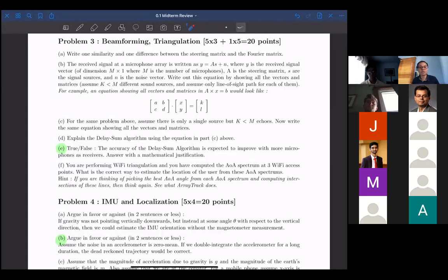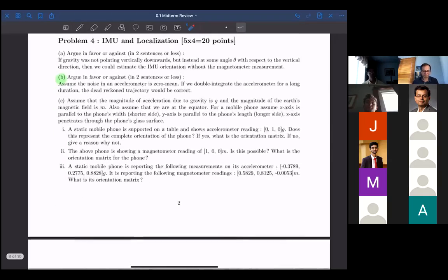But if I do 1,000 coin tosses, there's a much better chance that you're going to get 500 heads, 500 tails, or the deviation is going to be much smaller. So if you have more and more noise samples, the noise cancellation is more and more likely. And that's where the gain is going to come from.